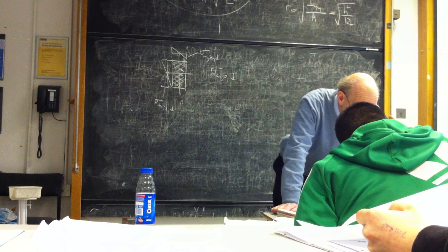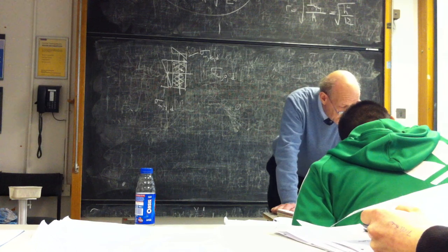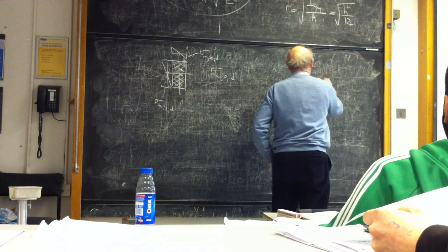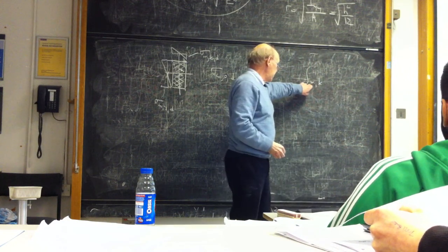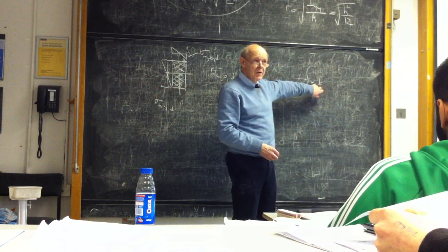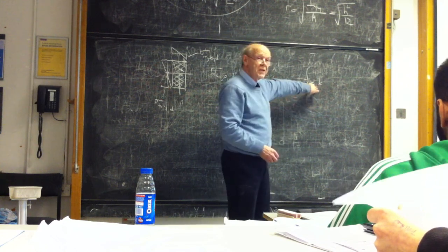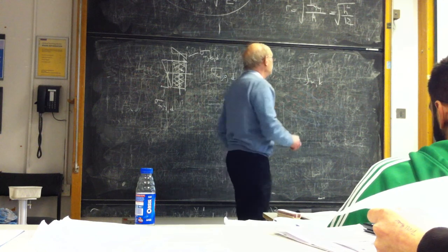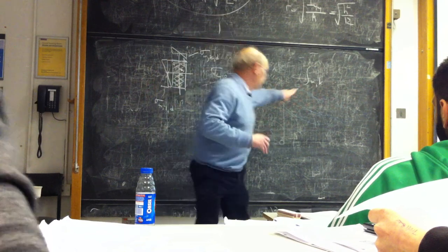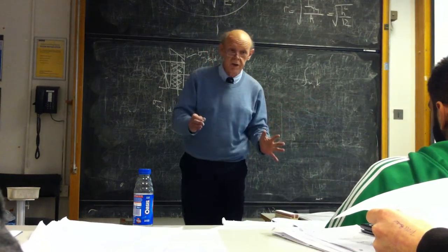So first of all, what's the permissible stress in bending? It's the FMK, which is the bending stress characteristic. Why characteristic is spelled with a K, I don't know. Perhaps it is in German, I'm not sure. Does anybody speak German? Yeah, I think it is spelled with a K, isn't it? So that's what you get in the laboratory if you tested a piece of timber. Does the M stand for material or...? M stands for moment, K stands for characteristic. It's, if you like, what they got off a laboratory specimen.